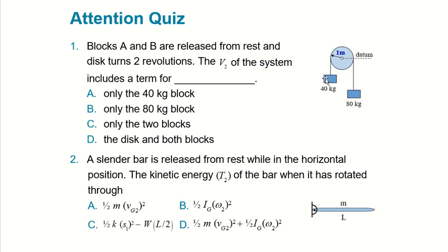This is where your kinetic and potential energies are transferring back and forth. The disk is just a medium, carrying the 2 weights, so it doesn't really move; it's just providing the angular velocity for them. When you deal with the potential energy, we're just measuring the vertical distance for these blocks, so we're going to choose C.